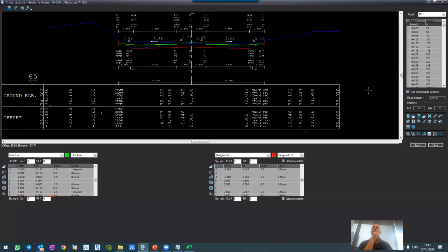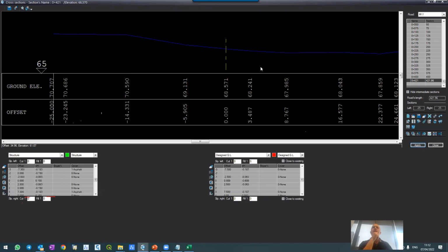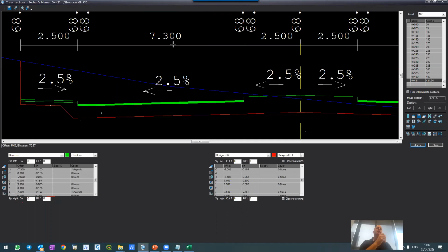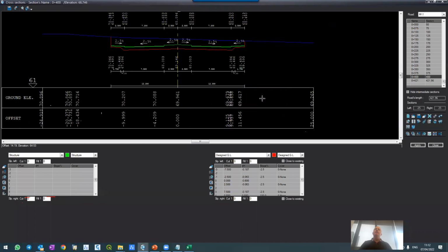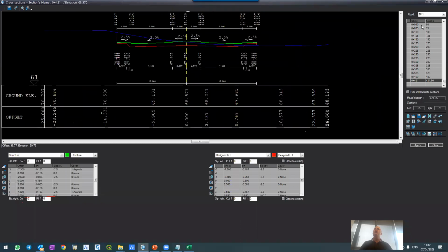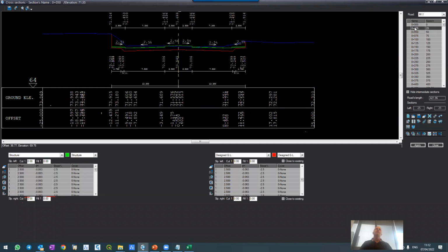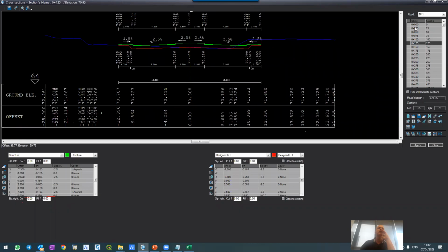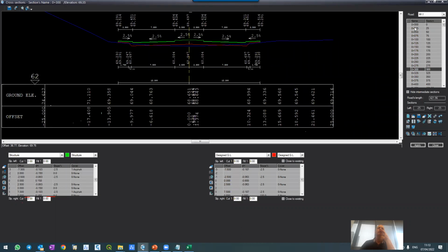I'm using this template all over my road. So I copy it, go to my last section in the list, this one, and paste. So this is how it looks in the last cross section. Okay, and now I interpolate. Now the system projected this cross section all over. So this is the first one, second, third, fourth. We can see what is happening to the road all along.